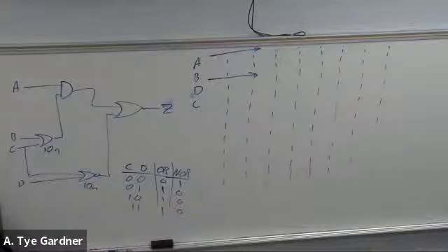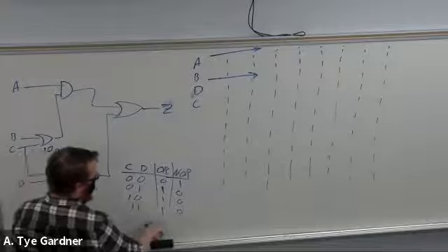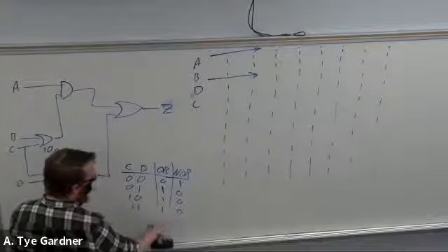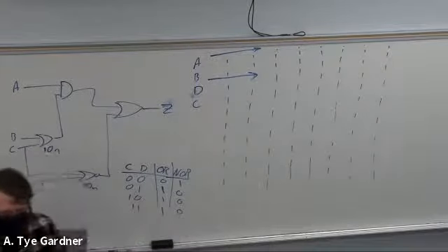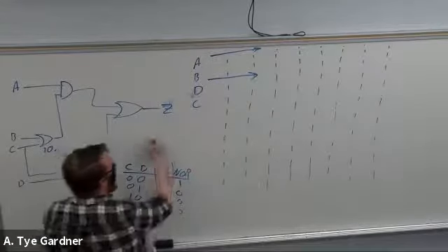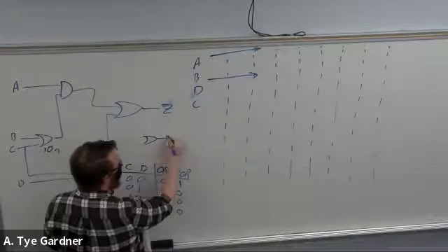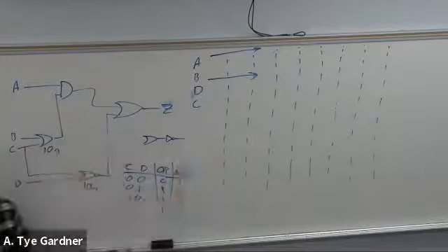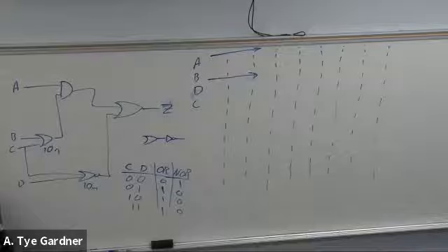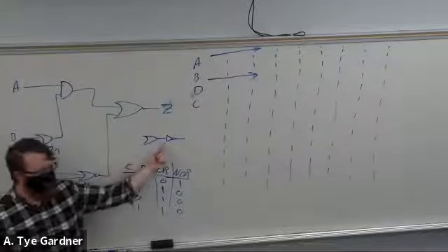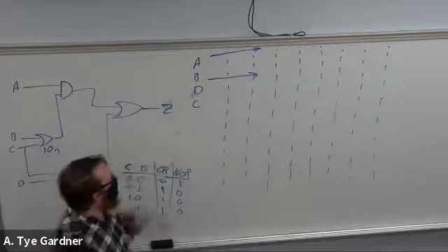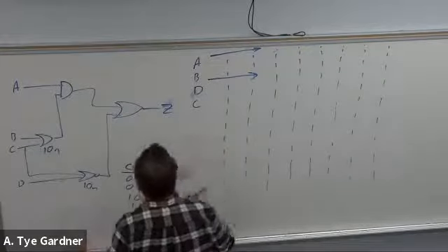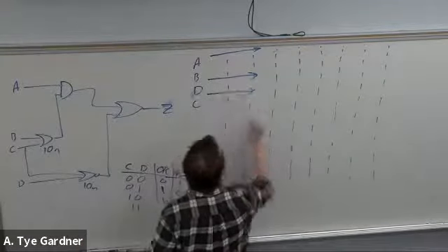Right? So that's how you find out what prime is. Okay, so therefore we just go ahead and look and say, well, it turns out that we need D to be 0, which is the same as an OR gate, which makes sense, right? Because if you consider your NOR gate as that, of course it's the same, right? The NOR changes nothing because I need this node to change and the inverter doesn't care. That's all a NOR gate is. So it stays the same. So we prime it the same way as an OR gate, therefore D is 0. Okay.